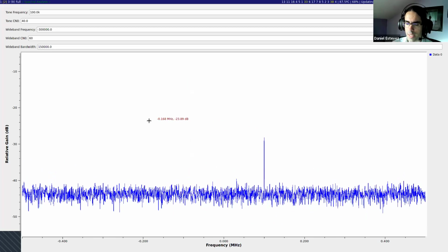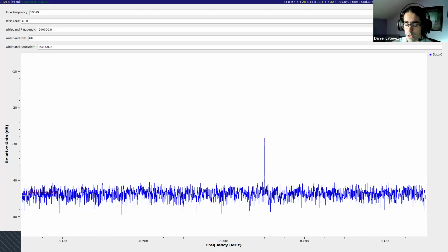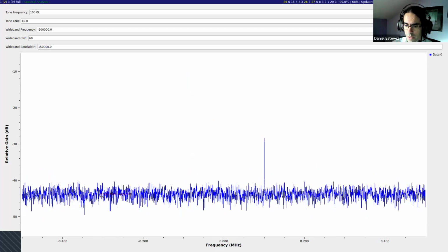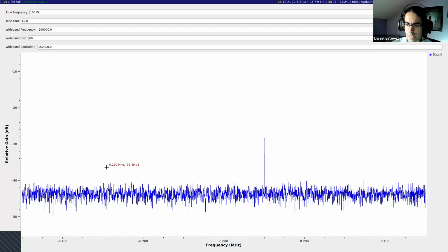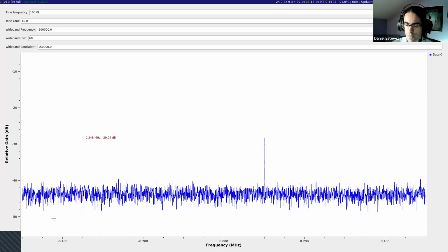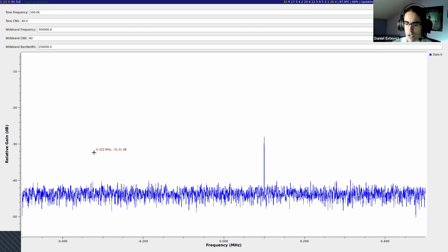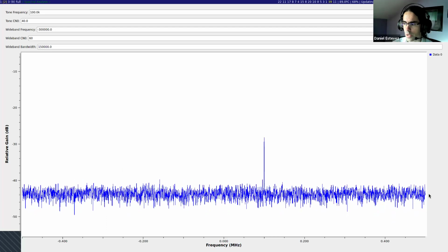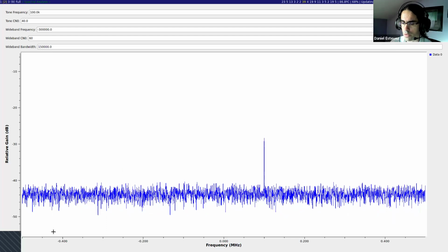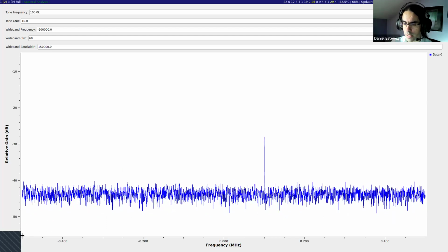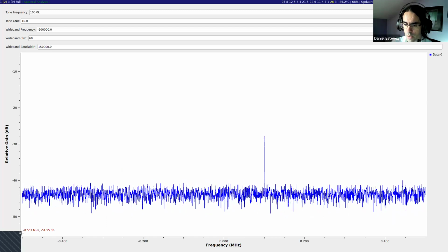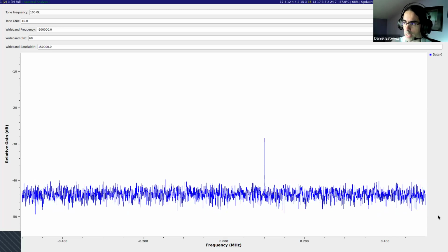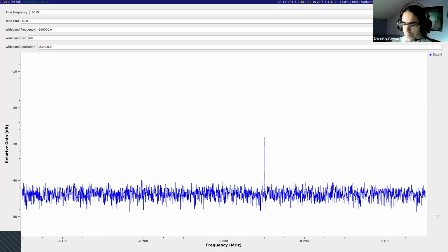And then if we think about Gaussian noise like this, it is something that on average is flat. So it's going to be the integral of a constant over a certain bandwidth. And that means that the power of this noise floor is proportional to the bandwidth we measure it in. We could say it is the whole noise power that we are seeing here. So here I have 1 megahertz of noise because my bandwidth is 1 megahertz. You can see that it goes from minus 500 kilohertz to plus 500 kilohertz because my sample rate is 1 megasample per second.